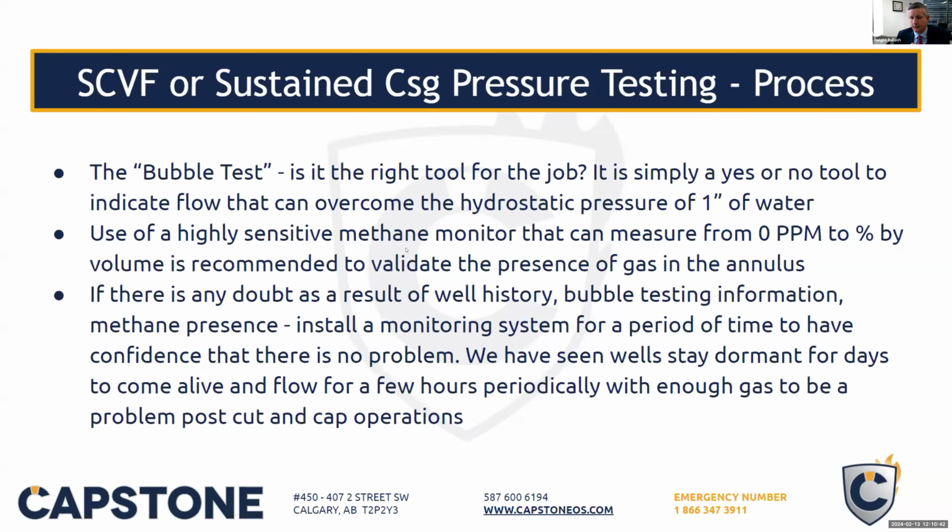We recommend that to validate the presence of gas in the annulus. If there's any doubt as to the result of the well history, bubble testing information, or methane presence, we recommend you install a monitoring system for a period of time to have confidence that there's no problem. We've seen wells stay dormant for days, then come alive and flow for a few hours periodically with enough gas to be a problem post-cut and cap operations.